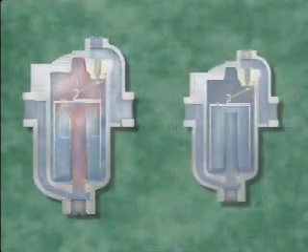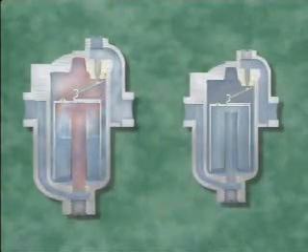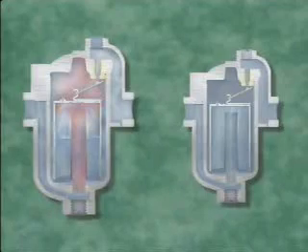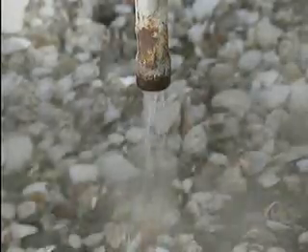On the other hand, a trap that's too small won't be able to handle all the condensate that's formed. This could lead to water hammer in the drip lines, or more likely, in the steam system that's being drained. What does this type of discharge usually indicate about the condition of a steam trap?